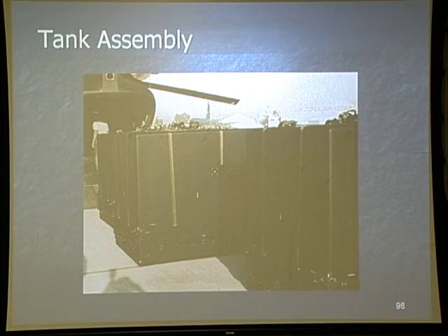And keep in mind that we can refuel all 6 tanks and 3 internals all simultaneously if we want to. Not advisable. Why? Because we want to monitor the flow. We want to monitor the fill port. So we normally do either the external and then the internals, or the internals and then the externals. But if we need to, we could do them all simultaneously.